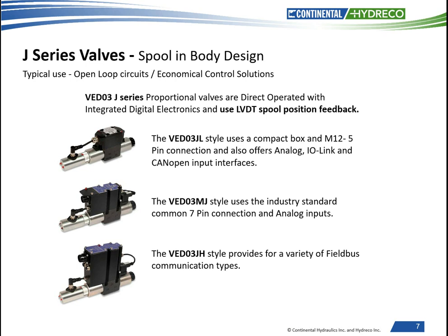Unlike an M or a G series type valve, which is programmed so that at maximum command signal this generates a capped amperage going to the coil for the 100% shift. This capped amperage limits the coil's maximum linear force, or the electromechanical force that pushes the spool against the spring, until the spring force and the coil force are equal in value. And that's where the spool stops. Because we are controlling the spool position and not the maximum amperage, we can then send higher power levels to the coil for more force to push the spool to the desired position faster.